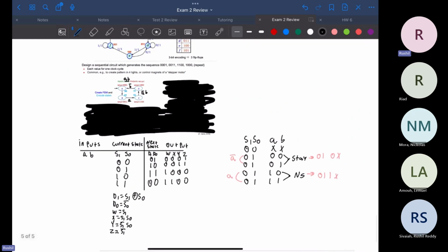You don't have to do it, just do a circuit for each one of those outputs. But you don't connect them, just separate circuits. That's it. I mean, you can connect them. Let's say, for example, W and X are the same. Their outputs require the same values. So you can have just one gate, with whatever going into it. This can be equal to W, and this can be equal to X. So in that case, you are technically combining them, but you're saving a gate in doing so. But we don't have to do that, right?